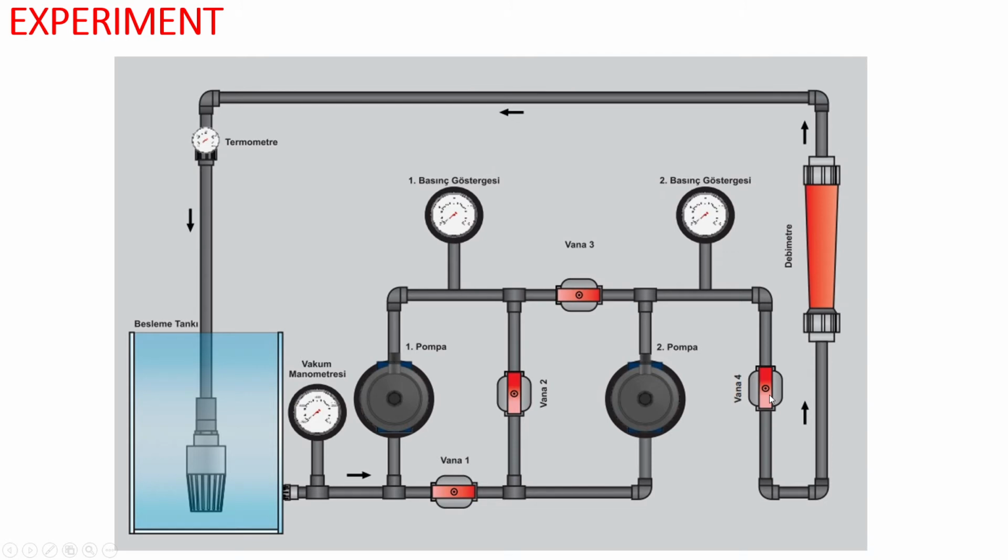For this experiment, the pressure is read from the manometers instead of head, since in university conditions the head or height of the water which is elevated by the pump cannot be measured. Also, the capacity of the experiment setup is not enough to observe head level. Thus, we move forward in calculation by using the volume-time method, which is mentioned in the lab manual, with measuring the pressure values.